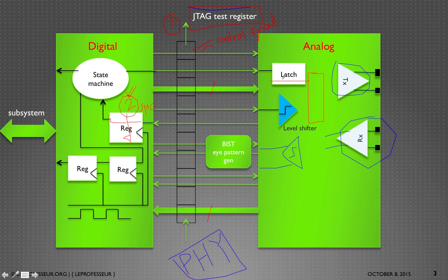They have to pay special consideration if they are not latching them. If it's just one signal but it's coming from a different voltage, they need to put level shifters. These are special considerations which are typically overlooked by digital designers as well as analog designers.